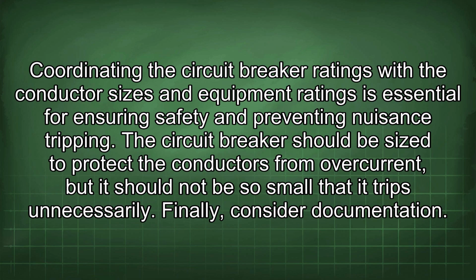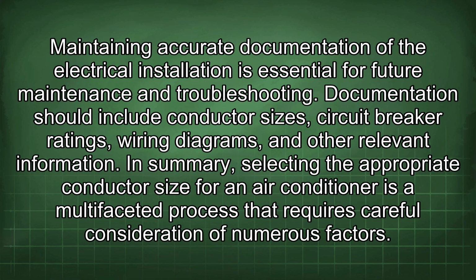Finally, consider documentation. Maintaining accurate documentation of the electrical installation is essential for future maintenance and troubleshooting. Documentation should include conductor sizes, circuit breaker ratings, wiring diagrams, and other relevant information.